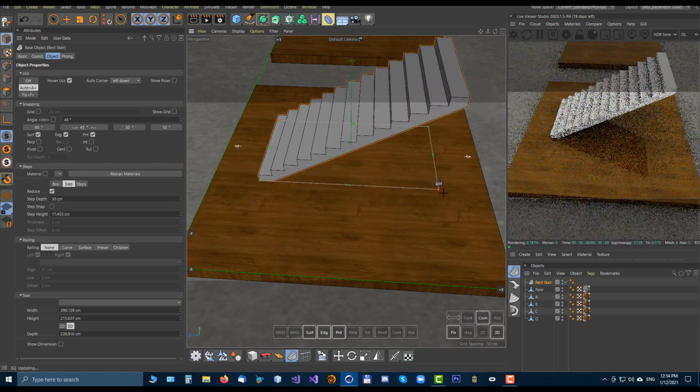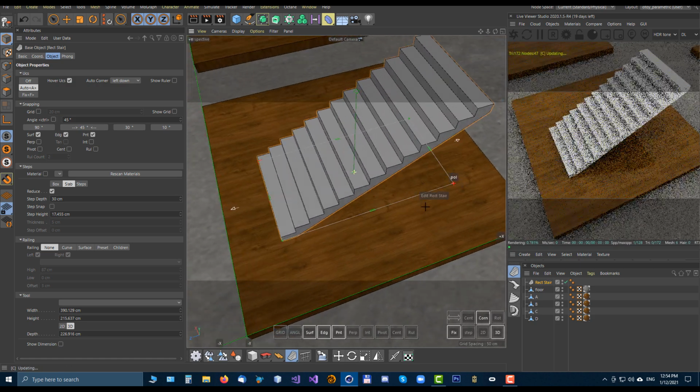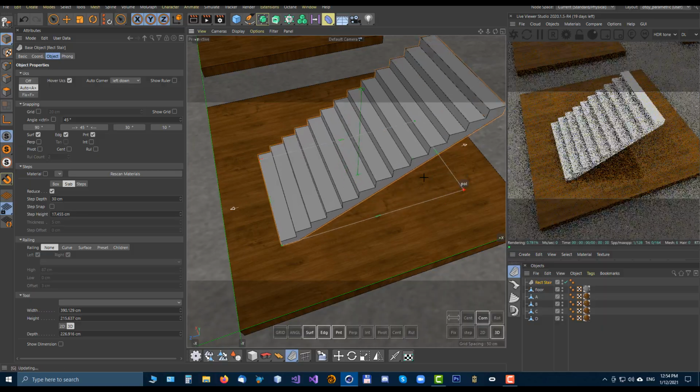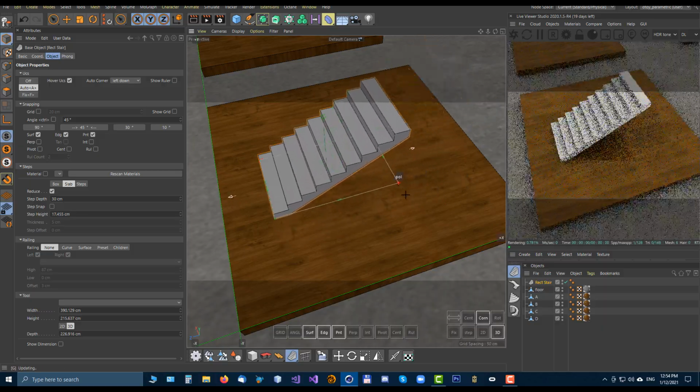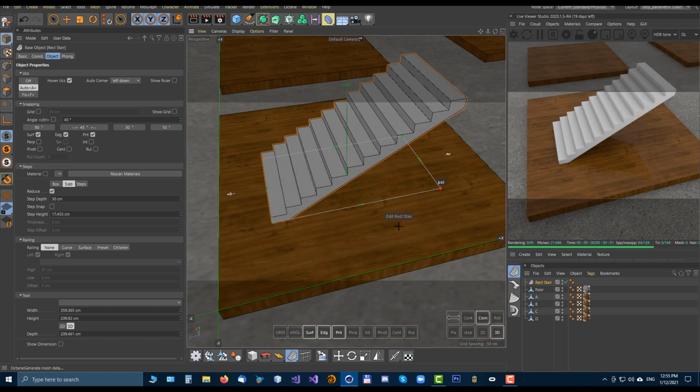You can fix the dimension of the stair and manipulate the object, then disable it and you can scale it again. So this is a very useful tool to fit stairs into any place of the building and place it and scale it there with handles precisely.